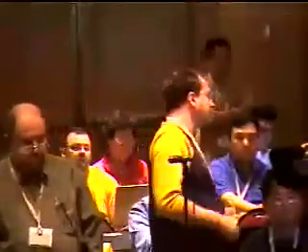So I think it's great the IEEE set a standard for the power budget for an individual SFP, but they probably had to say, guys, remember there's going to be 50 of these on one backplane. And that's a real problem. I've spoken to a couple of people both here and online, and it's just really hard. They're not designing equipment to supply that much current to the front chassis to drive long haul lasers. It's not there. Well, it would be good to see the vendors do that. If they know they're going to populate 50 in one slot, then I agree, they should be supplying the power budget for that.